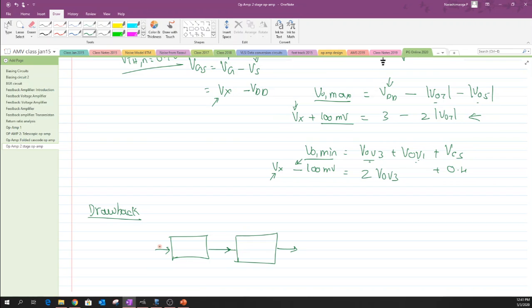Probably in your stability part, we will find a way by which we can ensure that the system will not get into an unstable condition, just by having an appropriate frequency compensation. But if the op amps are designed without any compensation, then having too many stages in an op amp will obviously lead to an unstable condition when we try to put a negative feedback around them.